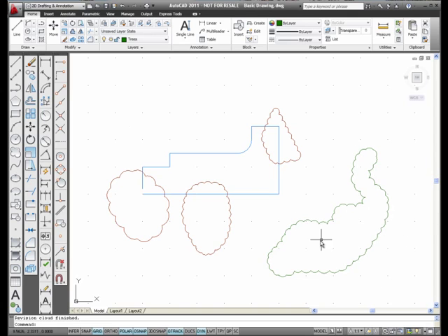But there's an opening right in here where there are no trees. What I'm going to do is I'm going to select the RevisionCloud again. I'm going to pick again, come close in like this, close it, and then I'm going to right-click on it, right-click again, and then I'm going to pick. It says select objects. I'm going to pick it, reverse direction, yes, and that's how you would do that. Notice what happened when I did. I could also do it. I'm going to go ahead and erase it.